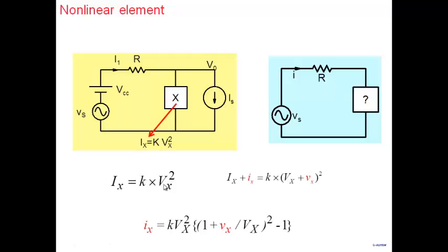After you've done that, then you can build an incremental circuit model here, plug it into this particular one, and get the answers that you see. You'll get the answers. That's the procedure. So the moment you get a nonlinear element, you have to do a first analysis of the circuit without the incremental change. Now this equation, because I've used a nonlinear element, the model is also nonlinear.